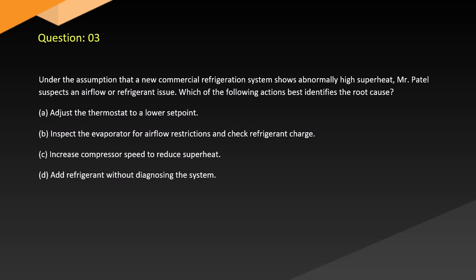A. Adjust the thermostat to a lower set point. B. Inspect the evaporator for airflow restrictions and check refrigerant charge. C. Increase compressor speed to reduce superheat. D. Add refrigerant without diagnosing the system.